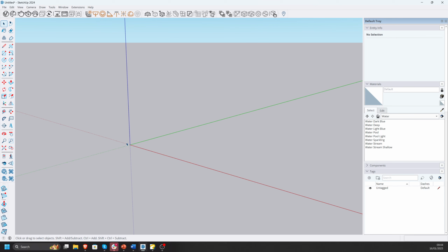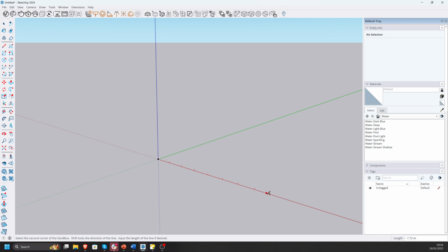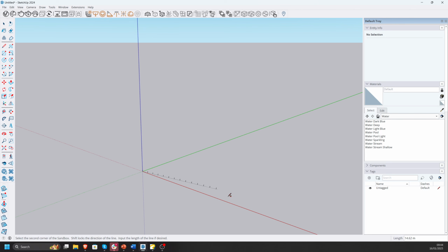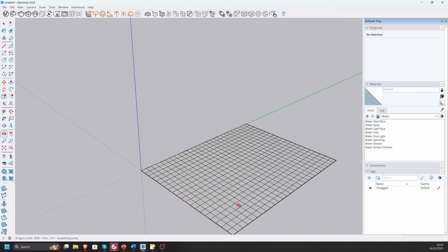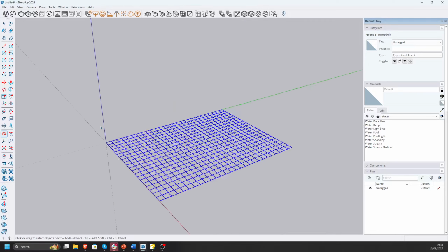Okay, what if we want to push it like in Blender or some software like that? We can do that even. We need to draw a mesh first. We have a tool for drawing meshes. It's right here. First we need to select the grid spacing, we select it on 1 meter. Want to go more detailed, select a few centimeters. We'll draw like this and this. There we go, a huge mesh.